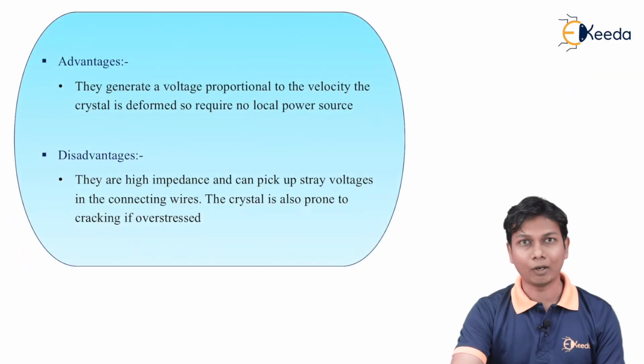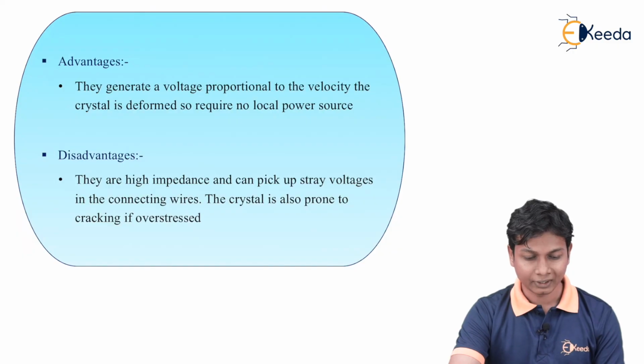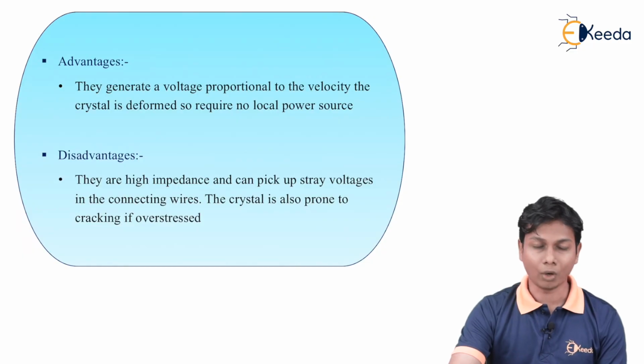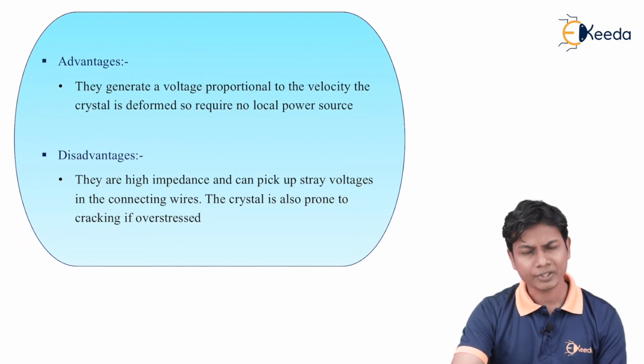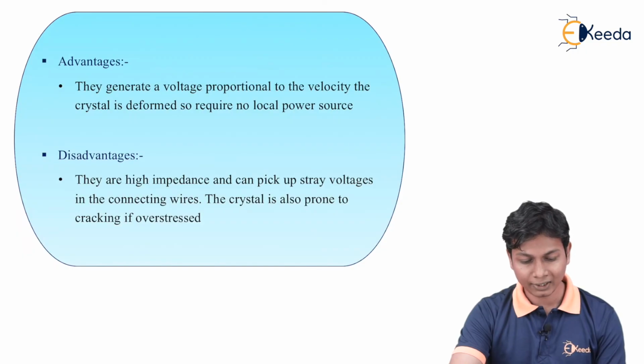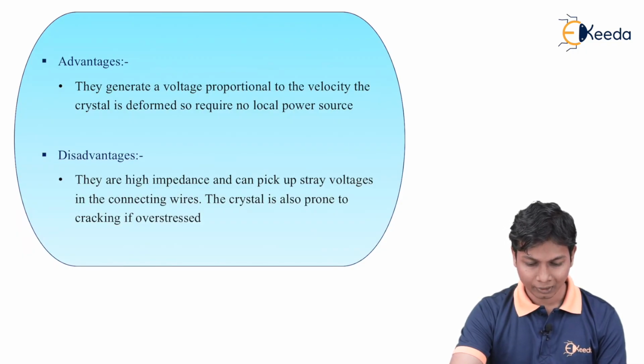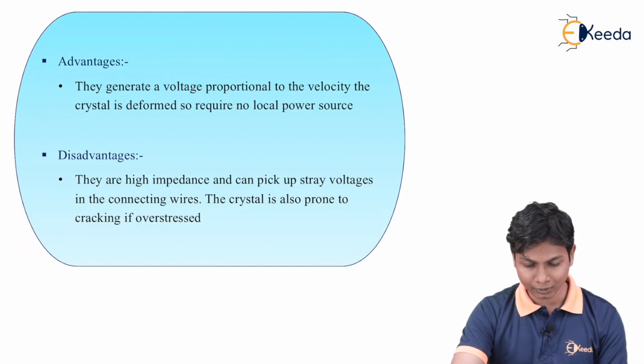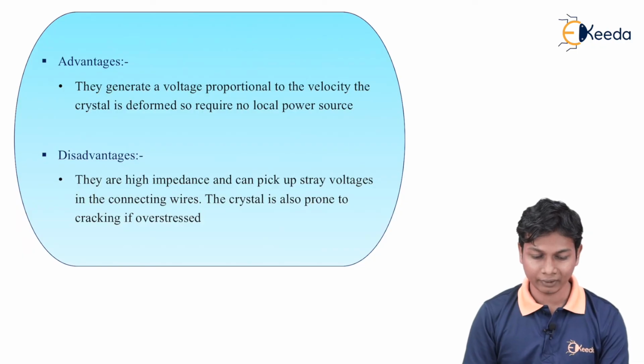Now, the advantage of piezoelectric is that it generates a voltage proportional to the rate at which the crystal is deformed, so it requires no local power source. It does not require an external power source because the crystal generates voltage as it deforms. What is the disadvantage? They are high impedance and can pick up stray voltage in the connecting wires. The crystal is also prone to cracking if overstrain happens.